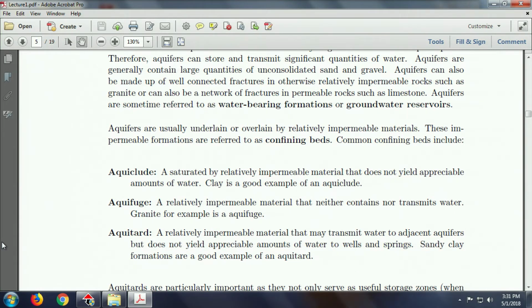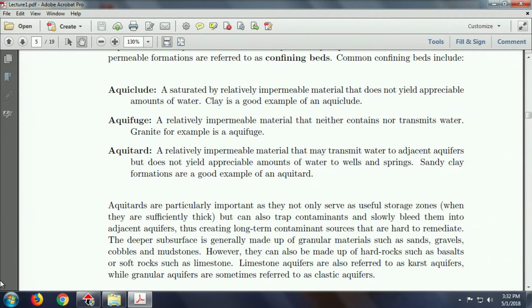It moves water very slowly, but it can be a huge problem when it comes to groundwater transport. If you have contaminated sites, the first thing you want to do in your geologic characterization is to look for those aquitards, because those aquitards are going to be a long-term source. You may remove that underground storage tank, but if that stuff has gone into the aquitard, it will act as a source for many years.